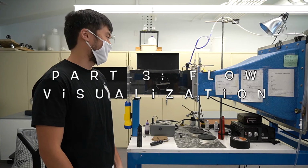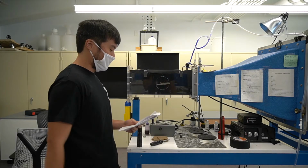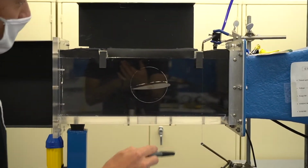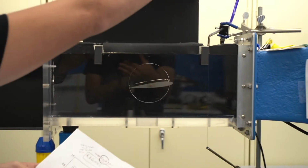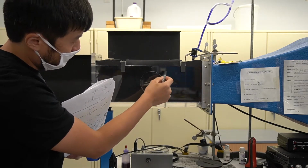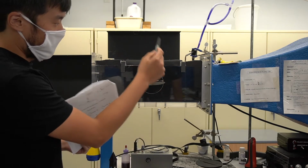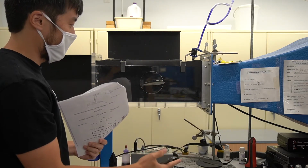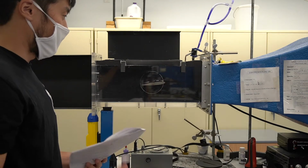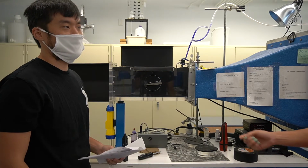So welcome to the third part of the lab where we'll be doing some flow visualization. Here we're going to be doing smoke wire visualization. You can see a wire that we run a current through. Attached to this wire you can see tubing. Through that tubing we pump model train oil through, and that oil will create droplets that fall onto the wire. With the current running through it, it causes the model train oil to vaporize and create smoke, which creates a smoke sheet, which we use to visualize the flow. This flow is running at lower speeds for clearer visualization, and let's get started.